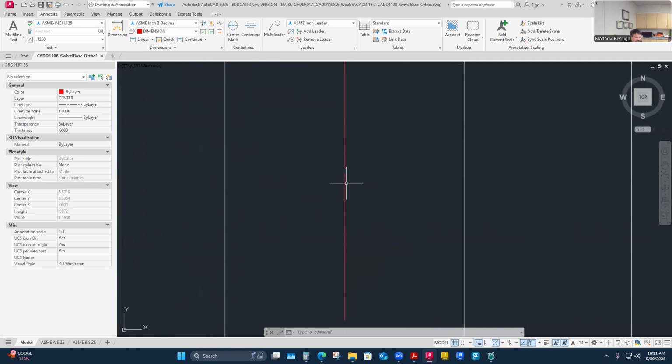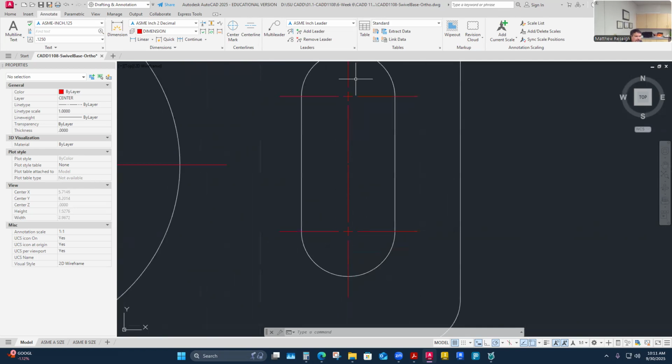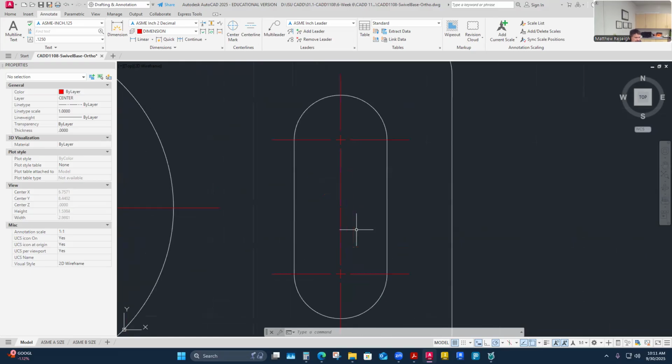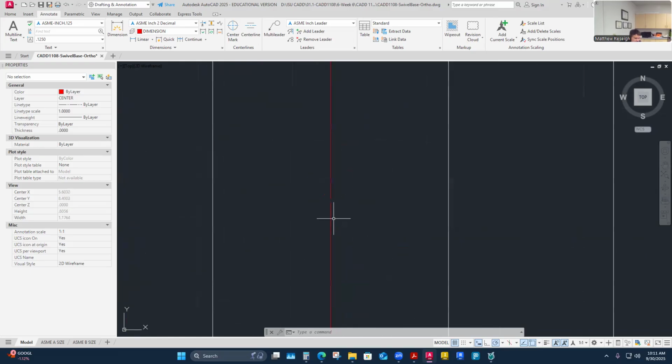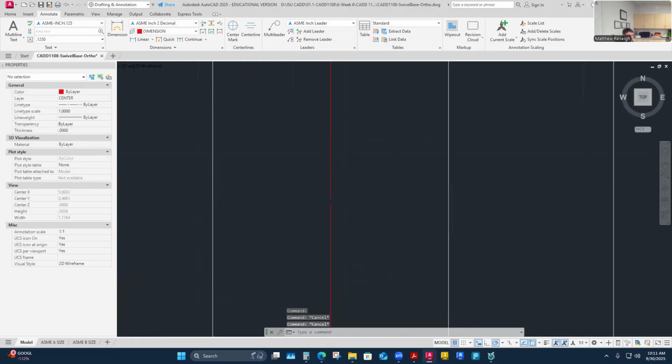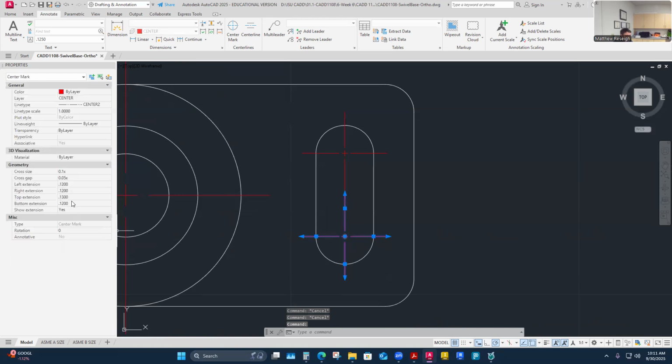But I generally like these to actually overlap, down the alignment of this slot from end to end, so I can show that alignment, whether it's vertical or horizontal. In this case, it's a vertical alignment, based on how my top view is. But yeah, pull those together, whatever rule I have to break to get those, whether I just pull the extension ever so slightly. Really, if I adjusted those extensions here, I'd probably get that overlap that I'm looking for.